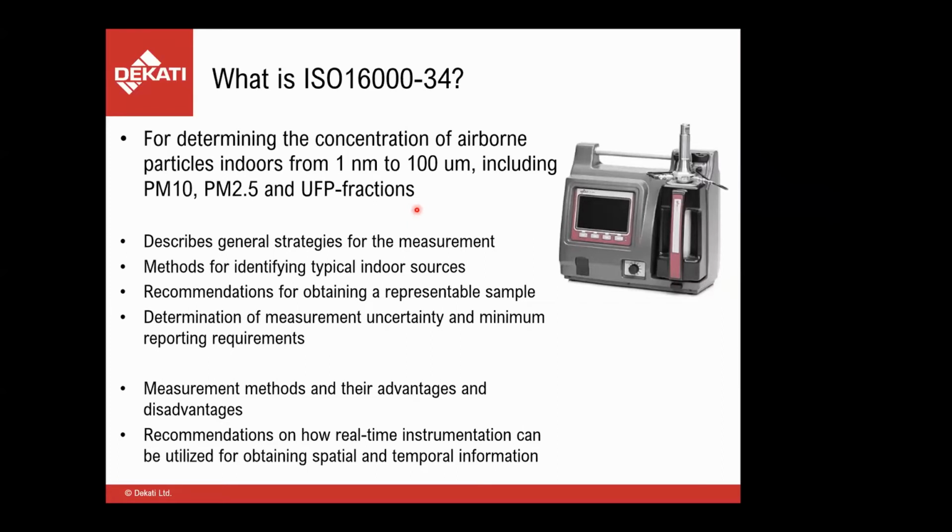The ISO 16000-34 has a very wide scope on what can be measured: particles from 1 nanometer all the way up to 100 micrometers, including PM10, PM2.5, and ultrafine particle fractions. The standard is very comprehensive. It describes general strategies for the measurements and methods for identifying typical sources.